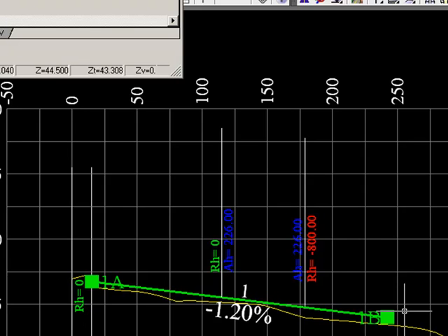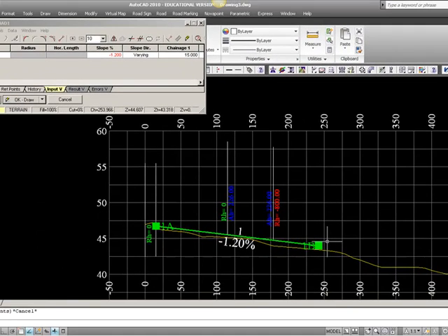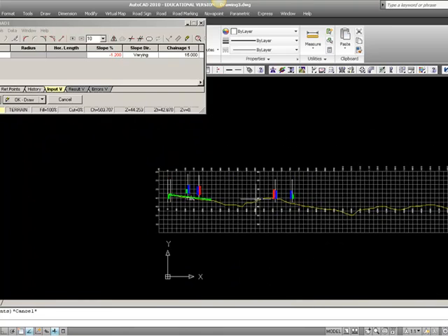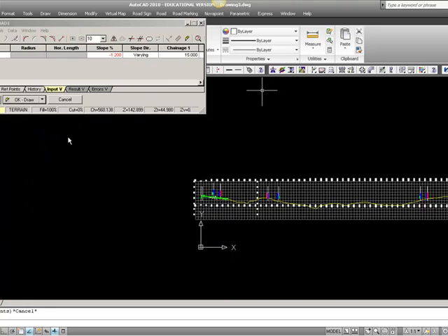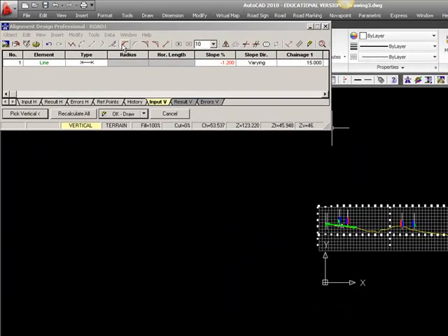and B. Now here it shouldn't be an issue turning the alignment back and forth, because we are working on the base of our horizontal alignment, and this has got the right chainage direction. The principles are then the same as for the horizontal alignment. I will need to go and finish over here by the church, so I will have to add some elements along the way to get my right vertical alignment calculated.